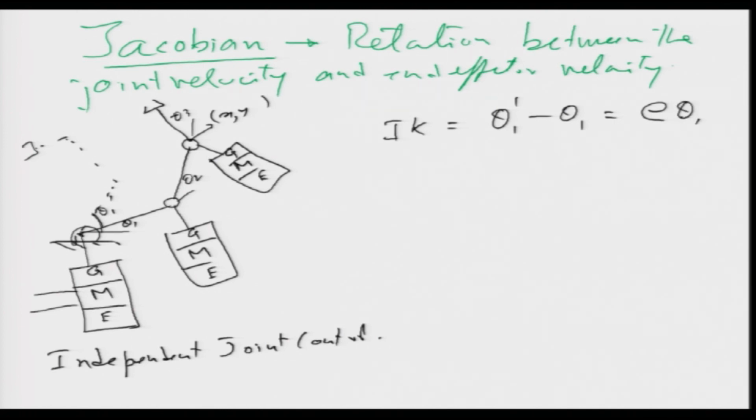And then we are going to actuate the motor. How are we going to actuate the motor? By giving a voltage, when we are using pulse width modulation, a PWM control. When I give a voltage to the motor, it will rotate. If the motor rotates, then the joint is going to rotate. If the joint rotates, then the end effector is going to move.